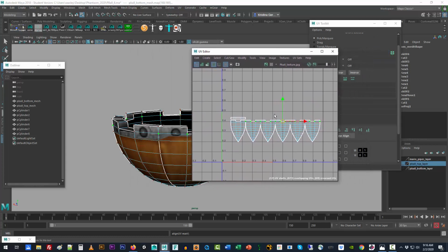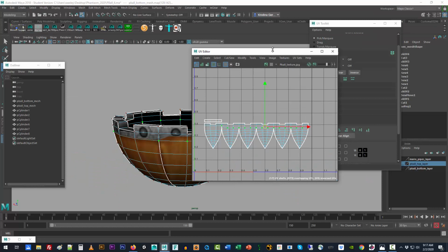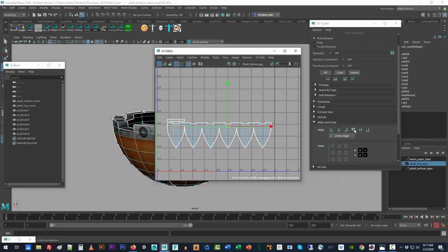And then the next level we want to worry about is immediately below it. And by the way, if this gets up in your face and you don't like it so much, press the minus key and it'll actually decrease the size of the controller. And of course it corresponds to plus as well. So I've got the limit I want to go to, and then I have all these other UVs here. And I'm going to go to the Align Up button here.